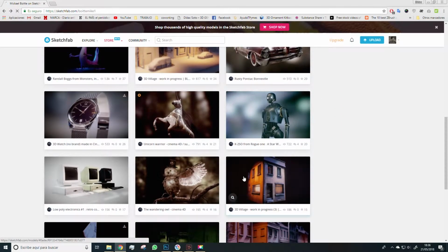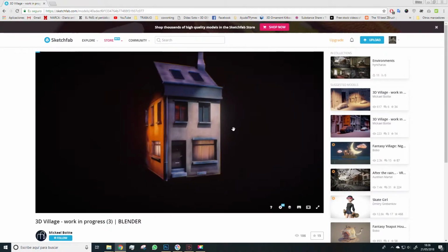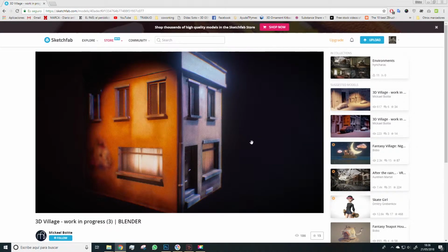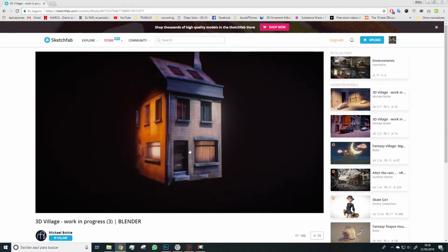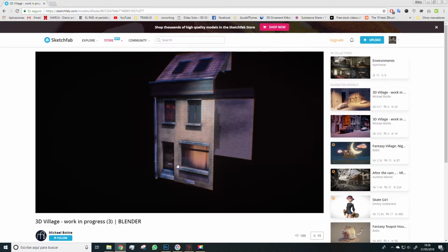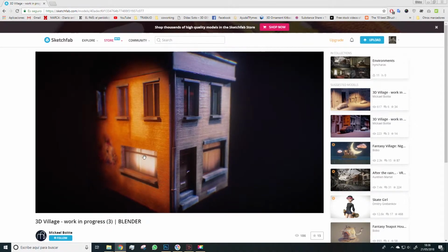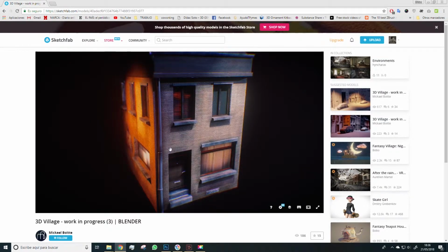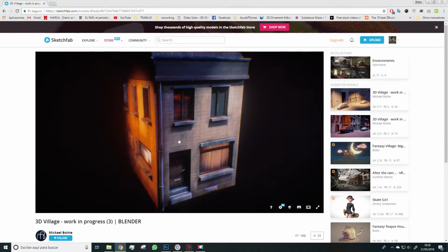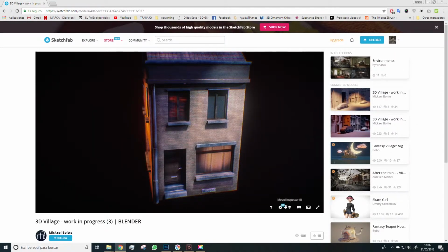For example, if you ever have to model a building in a night scene, you would need to light the windows. But obviously, you don't place a light behind each window. You just make the window's material light emitter. This way, we would get to illuminate the window without using lights. We would obviously use lights in order to illuminate the scene, but not the windows.